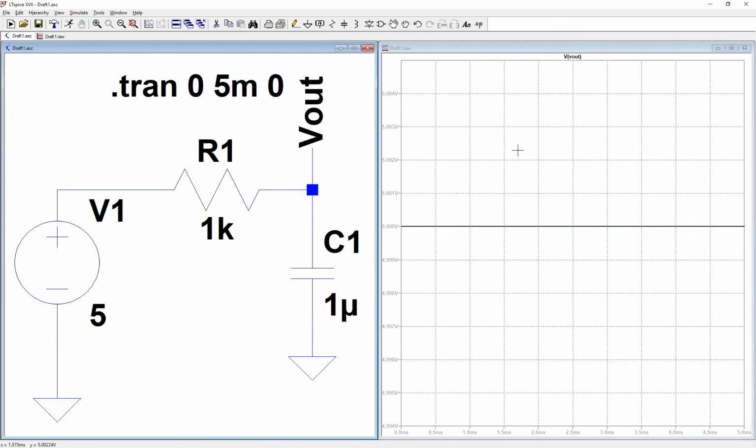Yes, so now the question is, why am I not seeing the charging of the capacitor voltage? Because that is what I was expecting. And again, the point of this simulation that I'm doing now is that the simulation, in this case, gives you an unexpected result. You don't expect the voltage here to be constant, but you expect the voltage to increase exponentially.